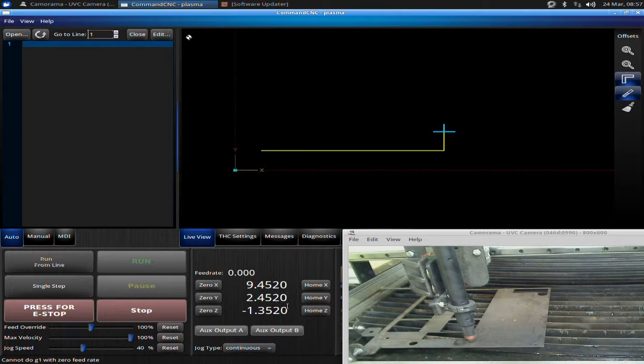So what I recommend is have yourself a piece of line paper or graph paper, something where each time you do a nest or you're doing a big cut, take a moment, write down these coordinates before you zero out for your job position, and then have them set aside so that if there is a problem, you can always get back on track.